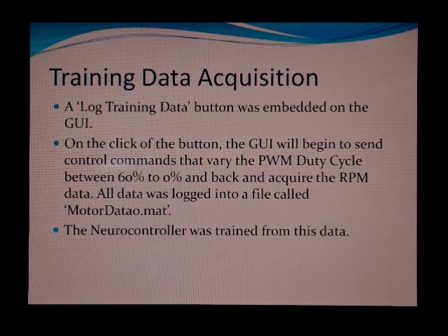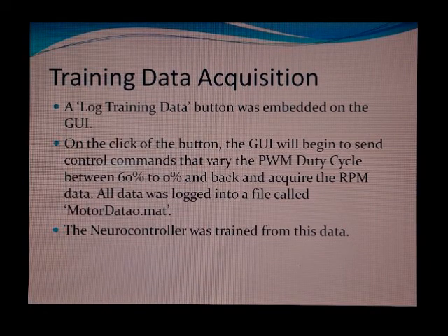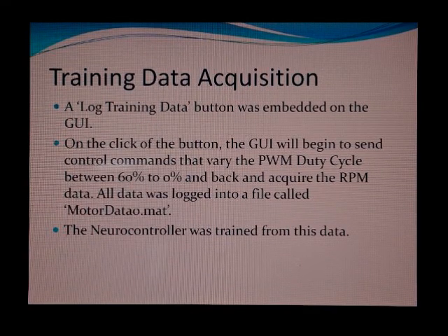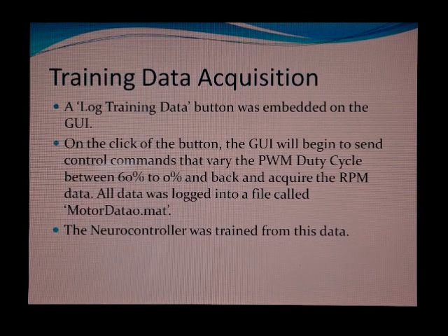And if I keep varying this duty cycle from 0 all the way up to 60%, at 60% it stops, so the motor does not move at all, it does not rotate at all. It had some nonlinear characteristics because of the H-bridge converter. So if I vary from 60 to 0%, I get a different response when I move from 0 to 60%.